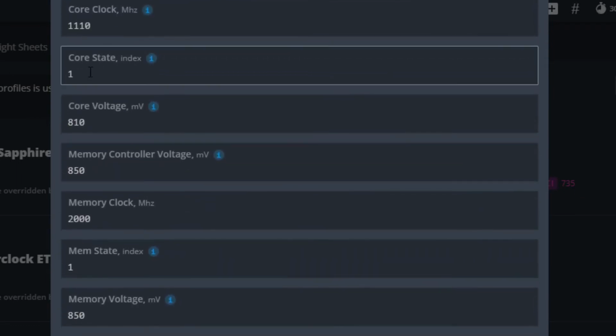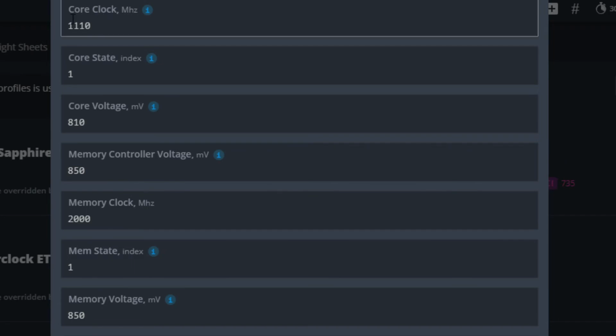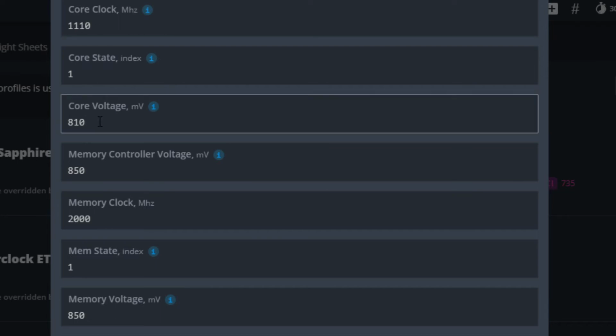But anyways, in summary, the way I like to approach overclocking is to start with a template. I have a couple of templates on my YouTube channel. I have a template for the RX 570 for Ravencoin, a template of example settings there. Example settings for Ethereum Classic. These particular settings are for Ethereum Classic or Ethereum. As well, I do have an example setting for Ergo. And mainly what we covered in this video is how I go about it: if a card crashes, I'm going to increase the core voltage if that's the one setting we're tuning with.